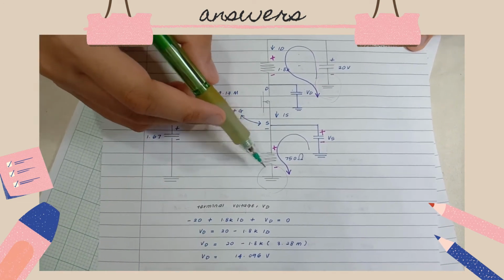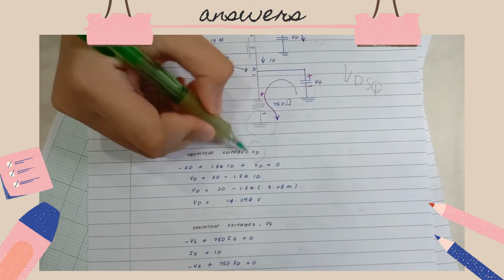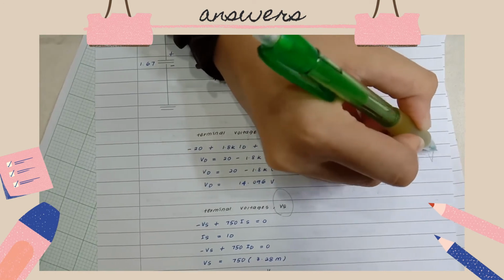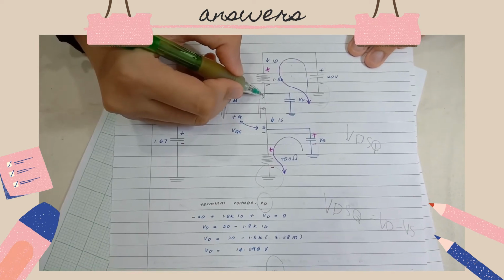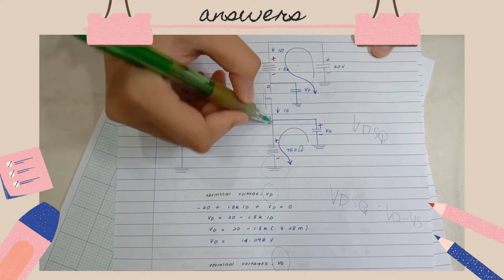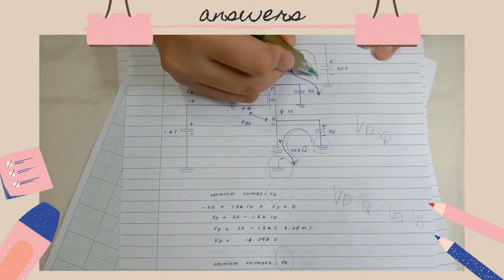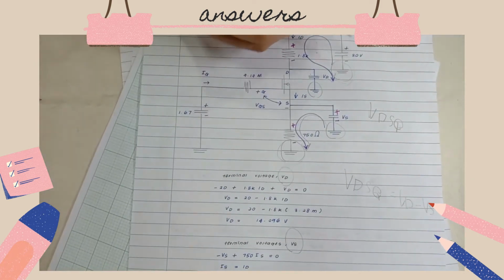I used to find the VDSQ by using value of Vd minus with value of Vs, because VDSQ is equal to Vd minus Vs. So at the terminal voltage Vd at point Vd and at the terminal voltage Vs at point Vs. Perform the KVL from this ground to this ground for Vs and KVL at this ground to this ground for Vd.